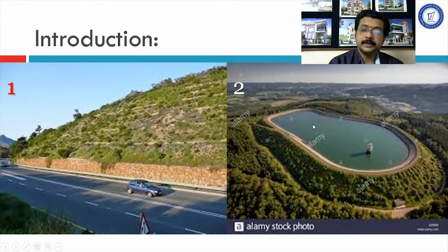Alright, hence the water pressure, the seepage pressure, and depending upon the properties of soil, whether this slope is stable or not, that we have to check. It is called analysis of finite slope. So a natural slope, that is hills, is called an infinite slope, and this earthen dam which we have constructed is called a finite slope and artificial slope.